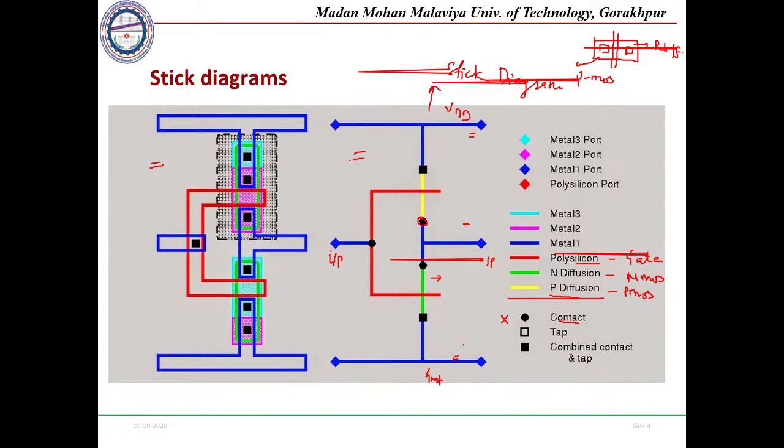To make the results relevant, the results obtained through pre-layout simulation and after layout, that is post-layout simulation, should match. To match those results, we should minimize the number of parasitics while designing the layout. That can be minimized by minimizing the number of extra layers that we use, or by reducing the interconnect requirements.